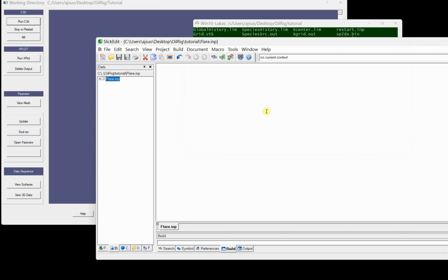Now the format of this file is quite simple. The first thing that you input is the number of line sources, and you can have any number you want. It could be 500,000, whatever you want, but in this case we're going to use 1. So the data that goes in there are the X, Y, and Z positions, and the X, Y, and Z cosine directions, the area of the subgrid in meters squared, and the length of the subgrid.